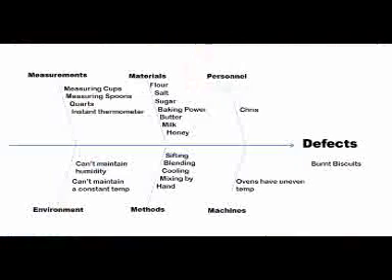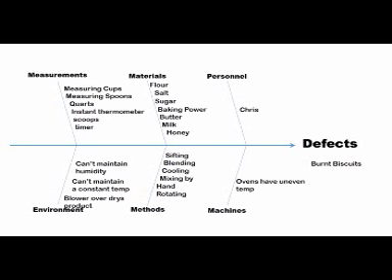Okay. How's that? So what did we learn from this second part of the process? We first learned that there were more instruments and measurements that we need to record. We learned that the environment, that the blower can over dry the product if they leave it in that one room. And we learned that because the oven temps are uneven, they have to rotate as a method.